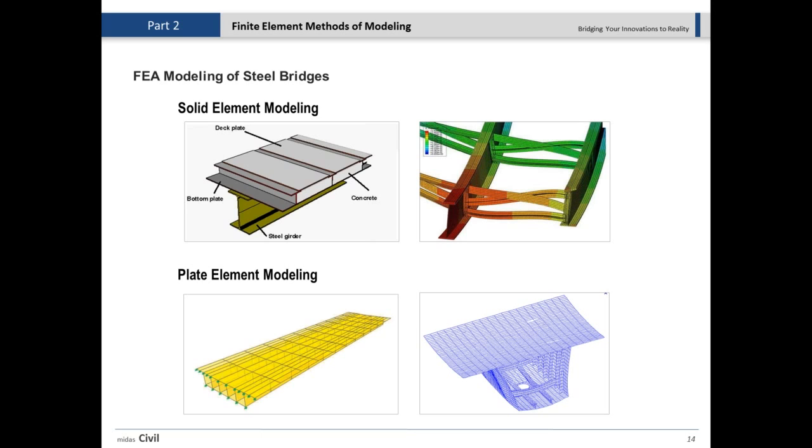Because of that, that's not very common amongst civil engineers or bridge engineers, unless you are doing a local analysis. If you want to study a certain part of a structure with more details and become very accurate, that will be a very good option, but not for a global analysis or modeling the entire structure with solids. So the next element that we could use would be plate elements.